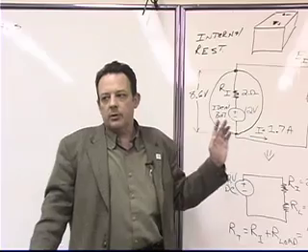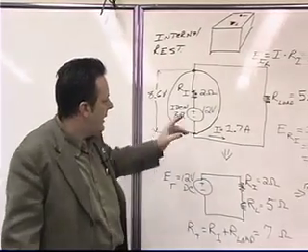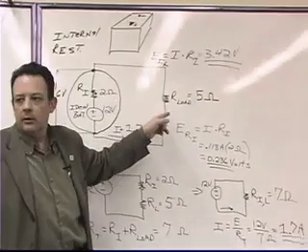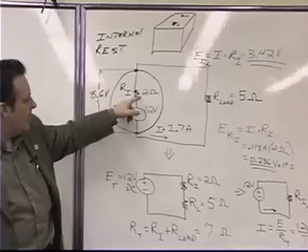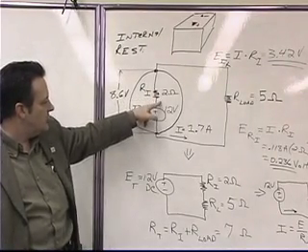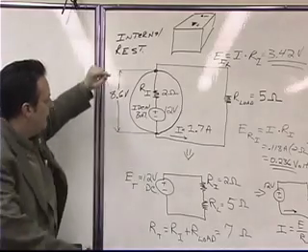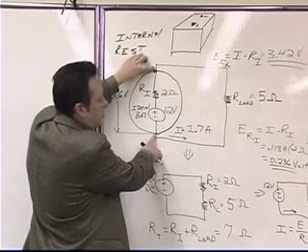That's really the picture on internal resistance. It's really not any more complicated than analyzing a series circuit and then changing the value of the load to see how the value of the voltage drop across the internal resistance changes, and subsequently the usable voltage at the output terminal of the battery changes.